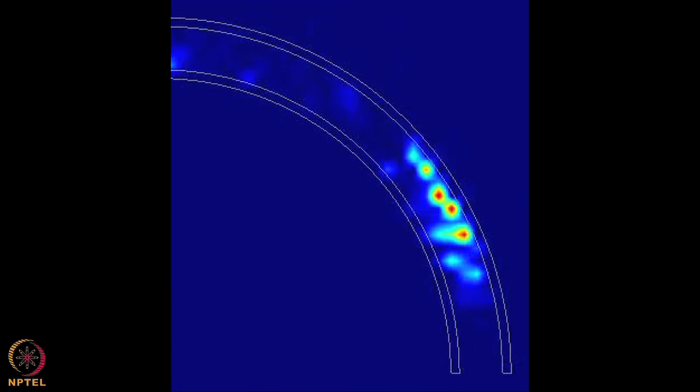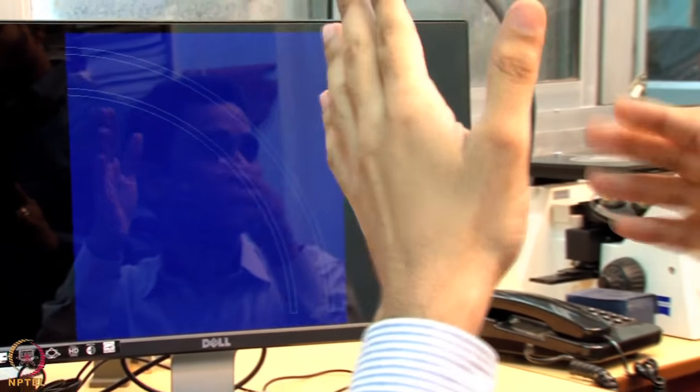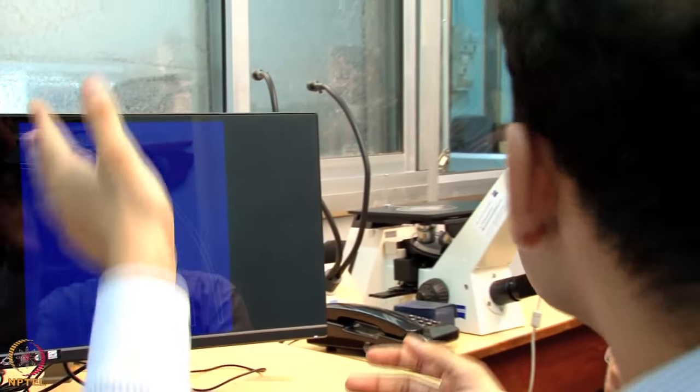Okay. So then, can you also show us when you have a bend instead of an elbow, a bend with a certain radius of curvature? This is for lambda by 3 discretization. So again, here the physics is not replicated properly by the discretization. When you have lambda by 3, whatever you're getting simulated is a noise which is not really clear, and there is so much numerical error. If you see the profile of this, if we plot electric field versus the distance it is traveling, that profile is not clear. It's not a Gaussian profile, which we are putting inside.